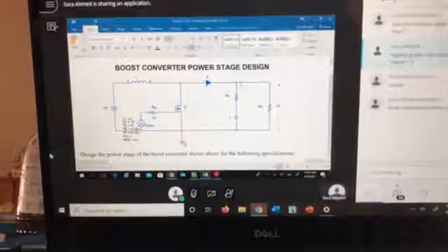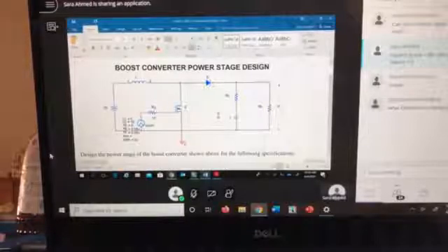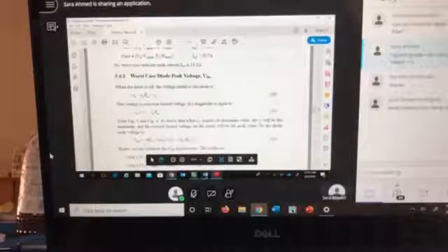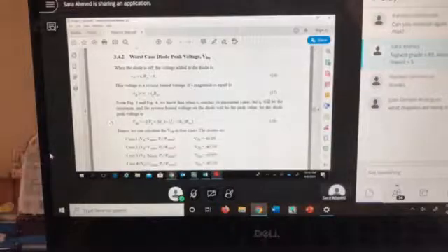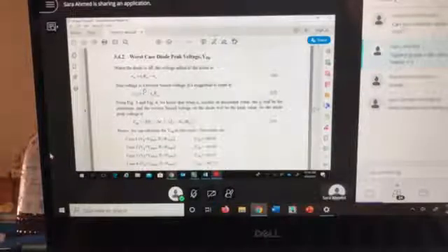You have the voltage across the diode, and then you have the output voltage. So this is the KVL on this loop. Okay? So that basically defines what your diode voltage will be. So I get my diode voltage. Again, my maximum diode voltage will have the voltage V out. So V out is the average value plus the delta VO.